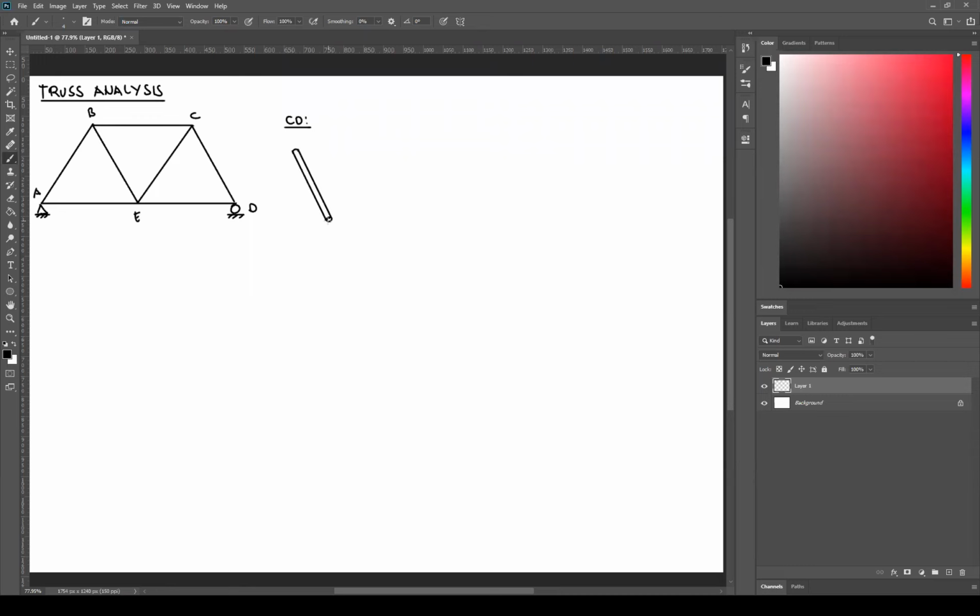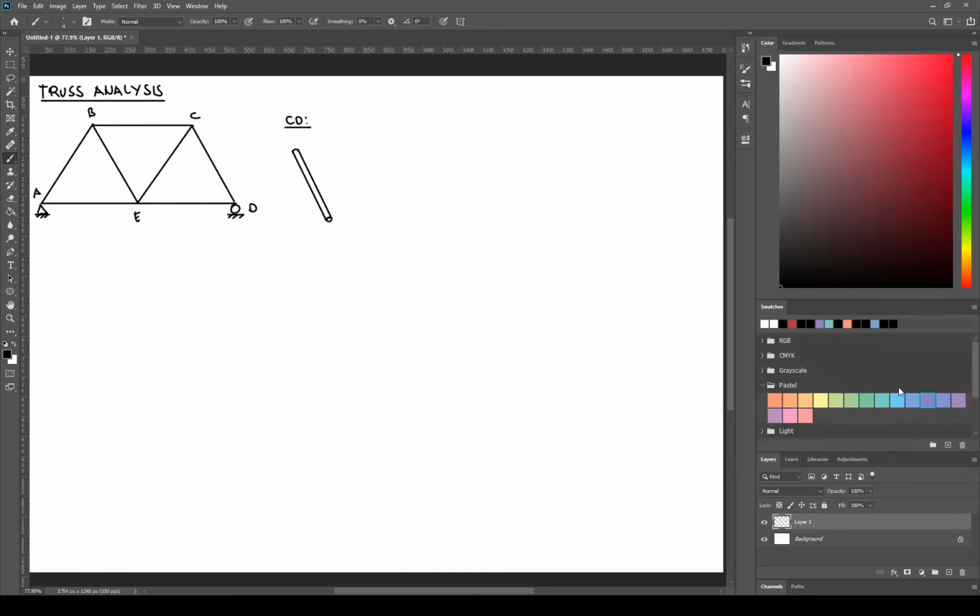And when the assembly is done right, at the ends we have pin connections. And when there's pin connections, that means your member will be loaded axially. So it's going to look something like this. These are the forces on your member, and they are actually equal in magnitude, F. They're along the axis of your member, hence they're called axial forces. Now another term for that, and a better term, is two force members.